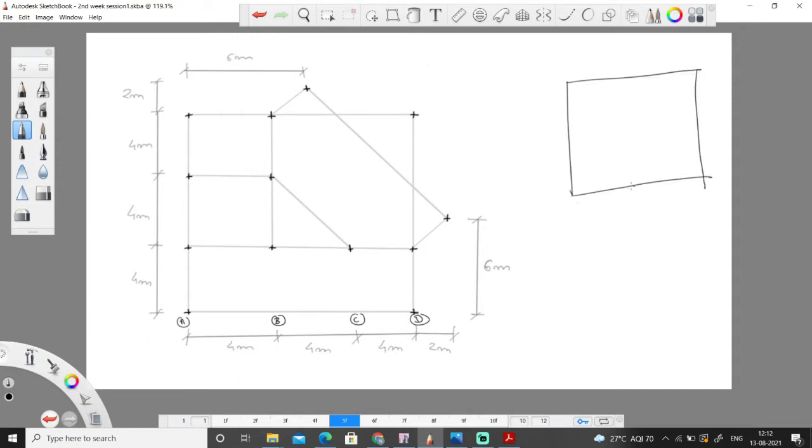The top, that is the plan, is this: from A to D it is 12 meters, and from 1 to the last point it is again 12 meters. Simply, we will form this grid by using the regular grid spacing system, and then we will input all these points by reference points. So let us go to ETABS.